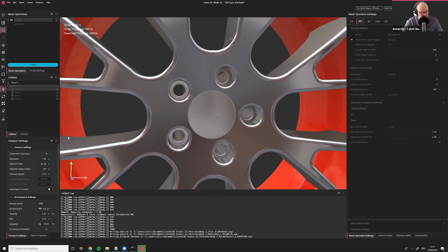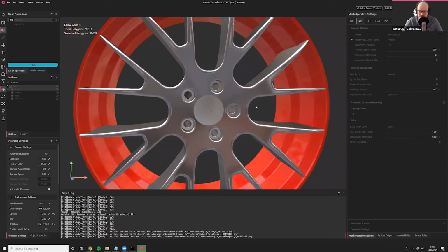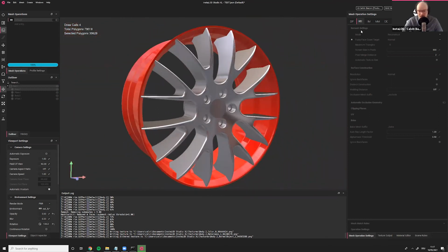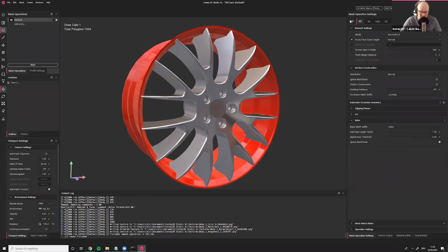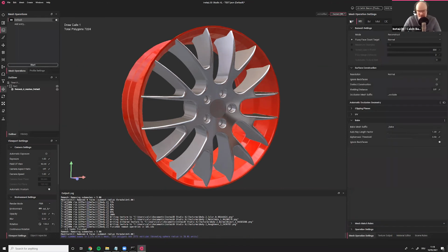Yeah, then in regards to the other functions, I assume you're talking about the different features. So today we've talked about remeshing. We did have a quick look at optimizing. So the optimizer is, in theory, pretty straightforward, right? It just looks at the same mesh, it takes the original mesh and it just removes edges in a really intelligent way, but that's basically what it does. So UVs, textures, everything, you know, vertex colors, all the metadata, everything just stays the same way because it's the same mesh, just optimized.